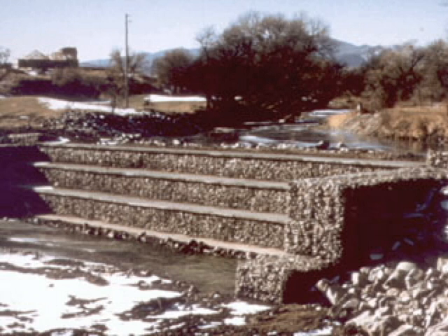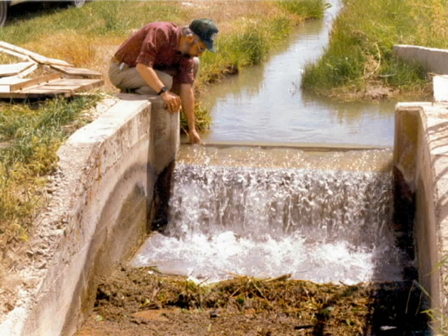The height of drop structures used to lower water from one control point to another should be based on the economics involved and the desires of the farmer. Since two smaller drops take more material and labor than one larger structure, the tendency in newly irrigated areas is to use fewer, higher drops to keep the cost down. In many of the older irrigated areas, the tendency is to use more small drops to eliminate deep ditches between structures.